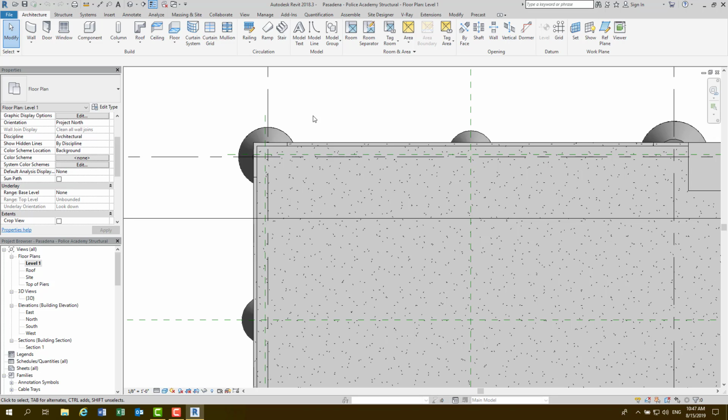Let's see, what other sizes do I need? I need a half. And the interesting thing about doing this too is you really got to decide what level of detail you really want to get down to. I tend to not necessarily err on the high side, but one thing that we also do here is 4D modeling, which is when you put the model against the schedule and you can see the model being built over time. I try to keep that in the back of my mind as I'm doing this because I want to make sure that we are putting enough detail in there that we can assign it to schedule elements and get a real feel for how the project's going to go together. So that's something that I've always got in the back of my mind.